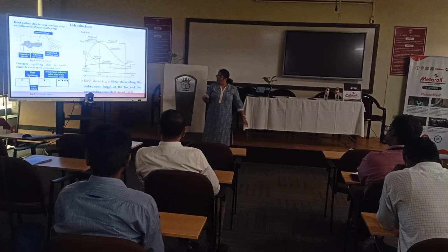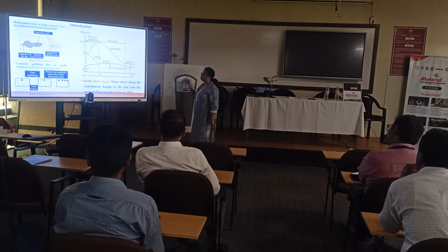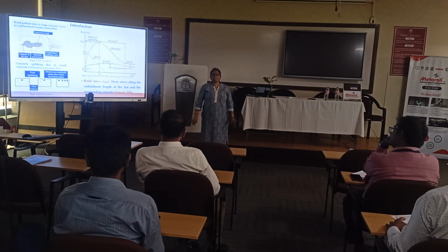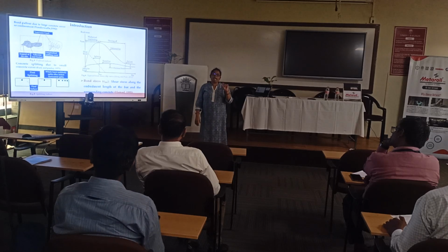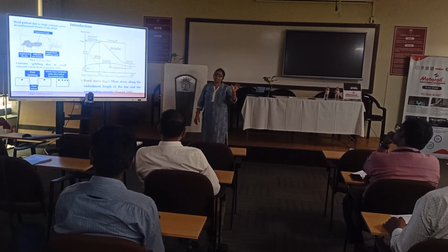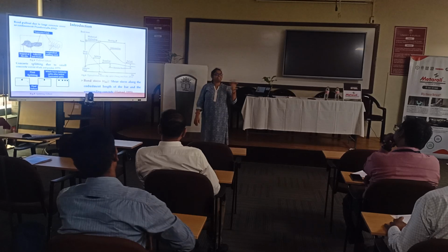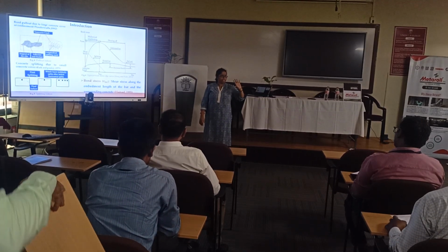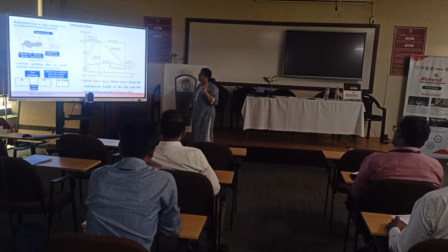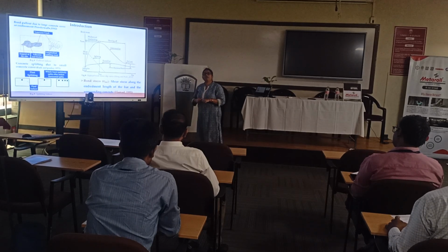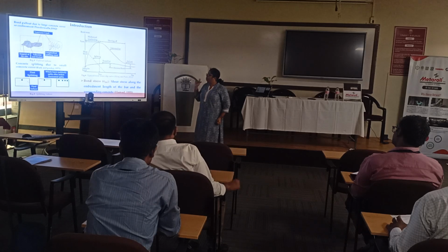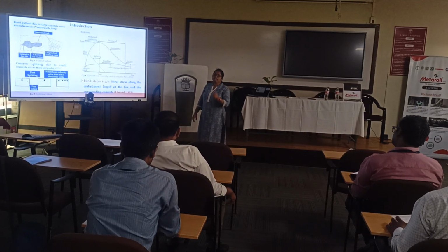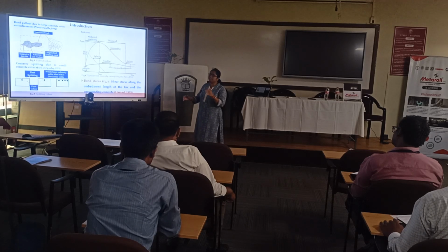Okay. Now, what do we talk about? The bond stress or bond strength, which is given in our code book. It says that based on the grade of steel and the grade of concrete, we choose. First of all, from the grade of concrete we get a value. Based on changing to a high strength HYSD bar, we increase it by 20%, 60%, whatever, right? That is what we do in assessing that. But it is where the failure happens. We now want to understand how the frictional or chemical adhesion has some kind of interaction force that is being developed or not.